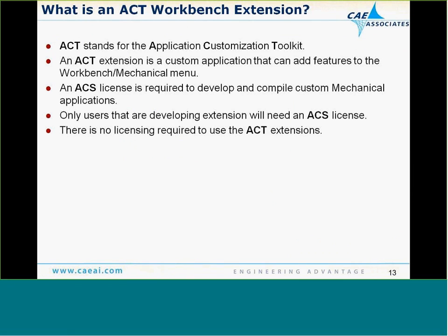So just briefly, what is an ACT extension? ACT stands for the Application Customization Toolkit. It is a toolkit that allows users to define custom applications for the Workbench environment. You do need to have an ACS license, that's the Ansys Customization Suite, in order to develop and compile your own Mechanical ACT extensions. However, you don't have to have an ACT license to use them. So if someone gives you a binary extension, or if you download one from, say, the Ansys website, there's no licensing required for you to use that.